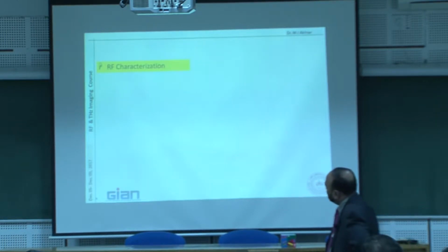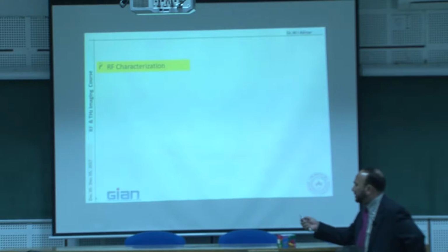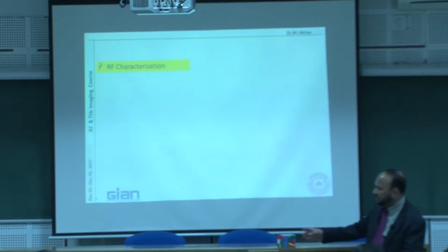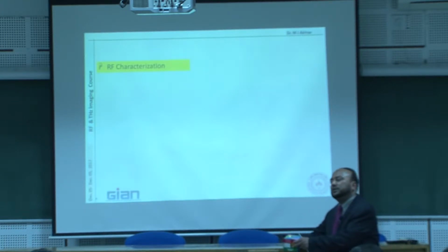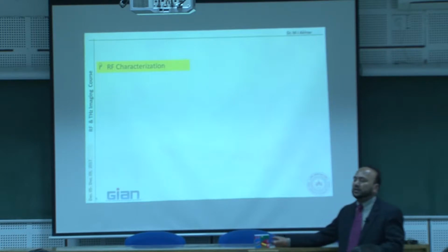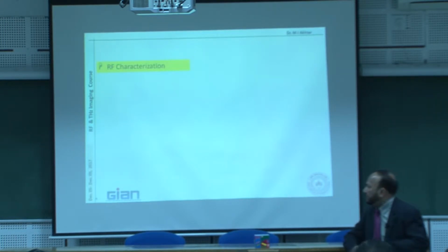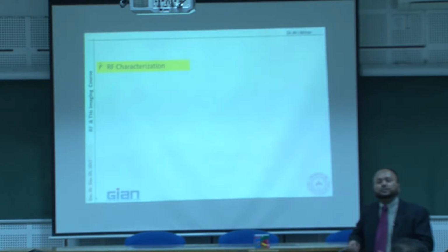So when I say characterization, we know the physical dimensions. If someone gives you a rectangular block and says I want to know its permittivity, they'll give you the thickness of the object, the height, everything is given. So now you have more known parameters, and the only unknown in this case will be permittivity. The problem is easy. So when I say characterization, it means you only need to know the electrical parameters; the physical parameters are known, whether it is thickness, height, or whatever you have.